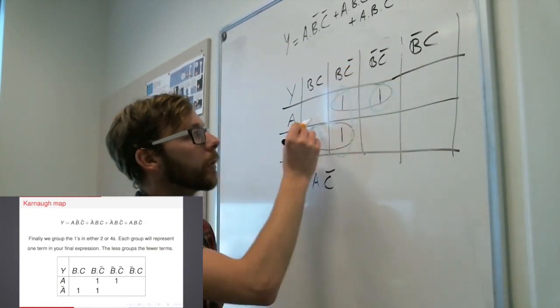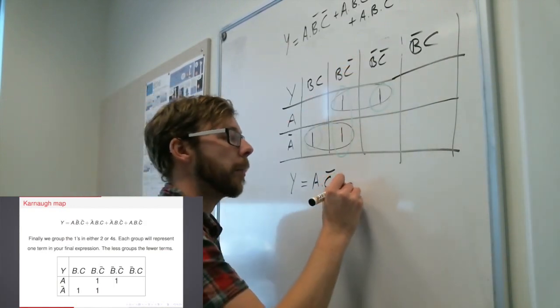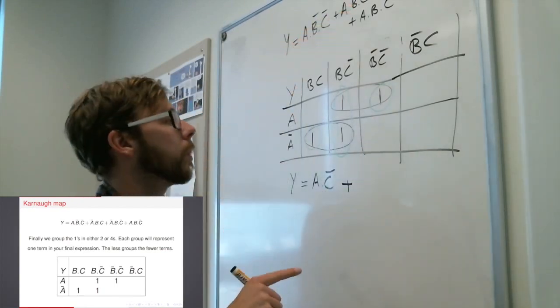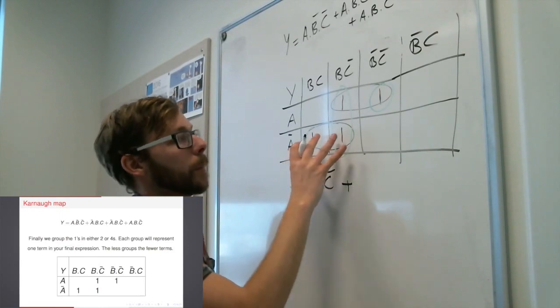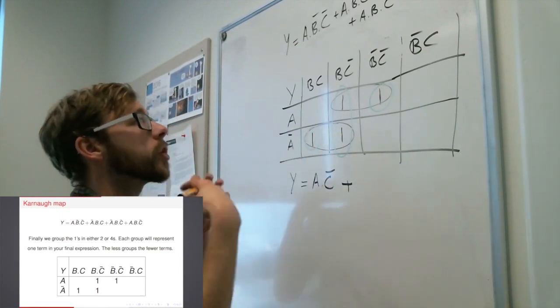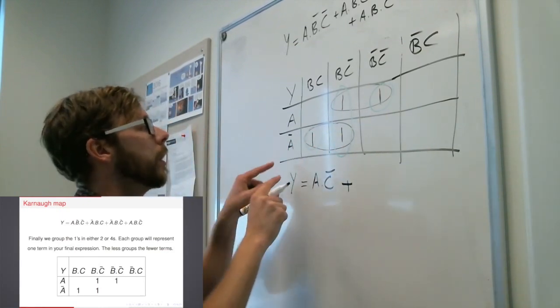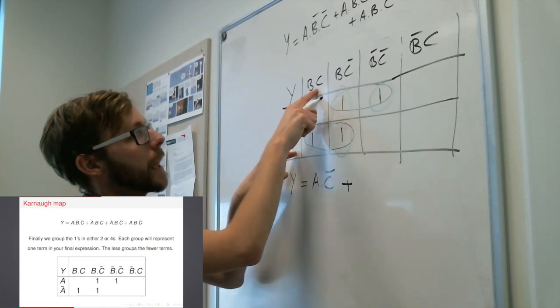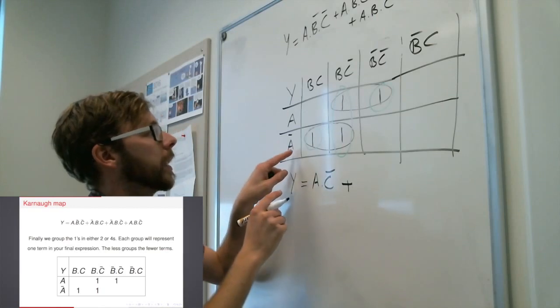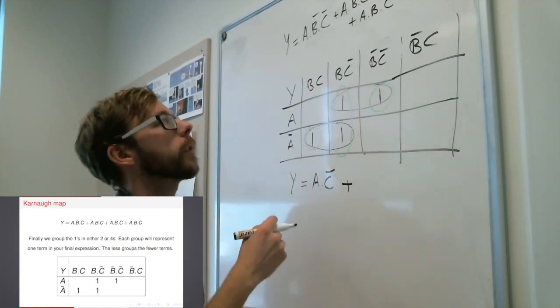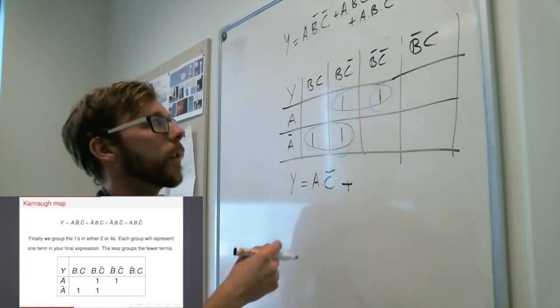And then my second term, which is this group down here, I put in OR, because we started off with ORs. And again, I say to myself, what's the same between these two expressions? What is changing and what therefore doesn't matter? This term here is not A, B, and C. This term here is not A, B, and not C. I can see that my not A and my B are constant through both. I can see that my C term is the one that's changing.